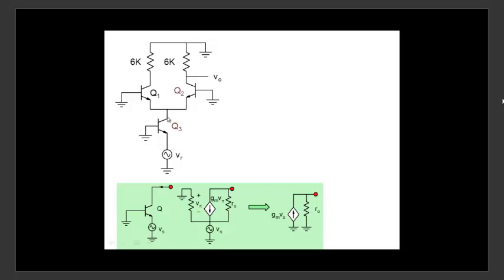So another way of saying it is, what you do is you build a Norton's equivalent at this node. But Norton's equivalent for what? For the circuit which is below that particular node. I'm only building Norton's equivalent for this part. Okay. Norton's equivalent for this part.